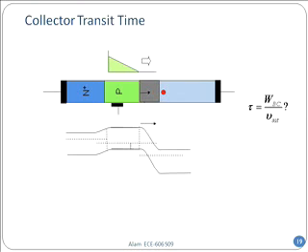Do you remember the image charge we talked about a few days ago? If you have image charge, then it will go slightly faster. As soon as the red electron gets into the depletion region, it will be imaged on the collector side. As a result, the current will begin flowing even when the red electron has not arrived at the collector.